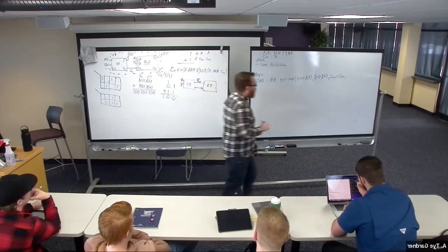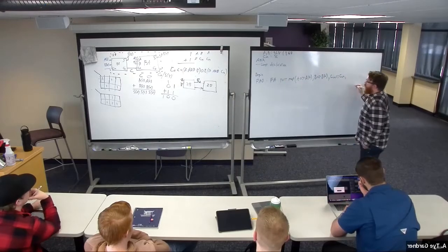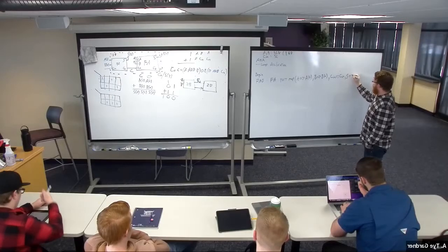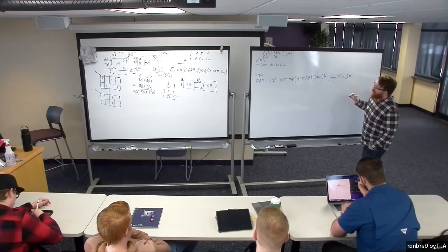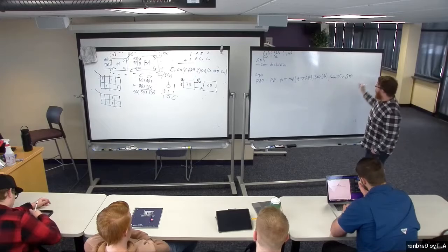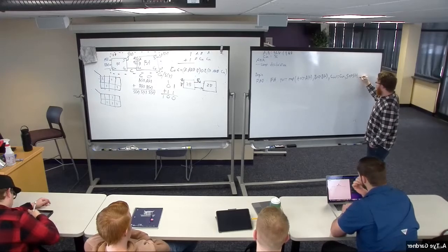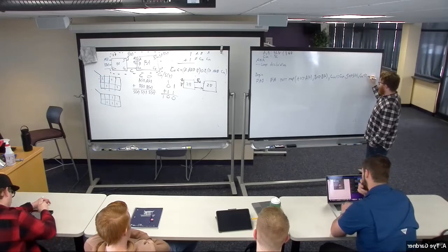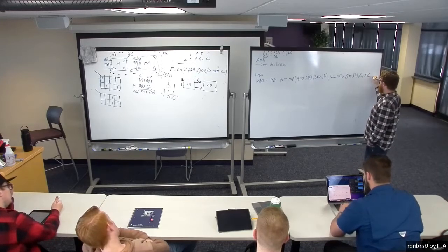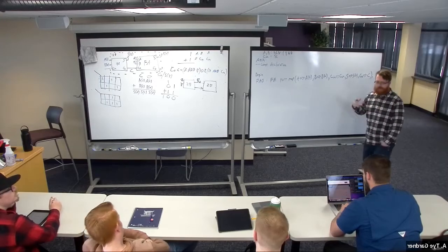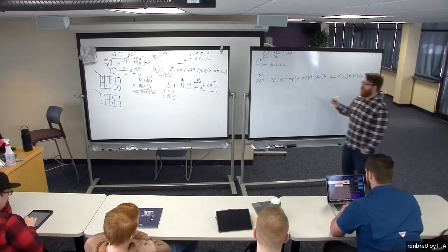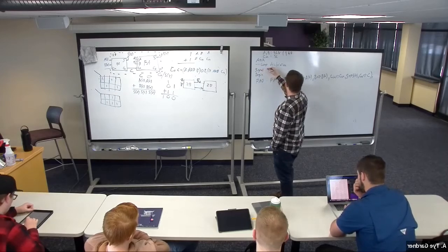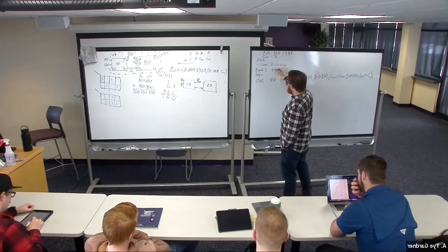So now I then can say, well, my remaining ports are sum, which can get mapped to, well, that sum is the first one, which is S at 0, and C out gets mapped to, we call it C. That C doesn't exist, so I have to go make it. Signal C is standard logic.